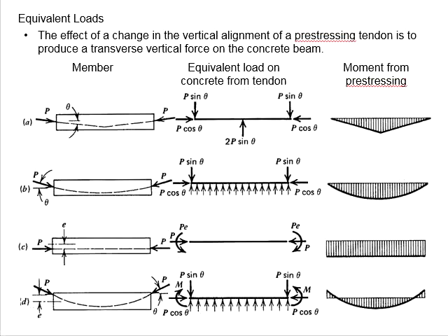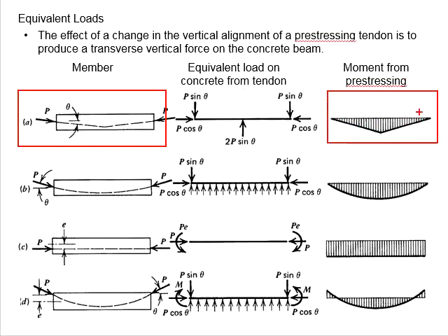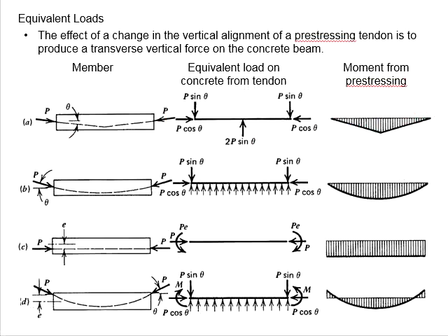It is noted that you do not necessarily need to totally eliminate the stresses in the member. It doesn't mean that this kind of tendon profile can only be applied for the point load, or that it is necessary for you to always use this to sustain the UDL. We have to go back to the fundamentals.